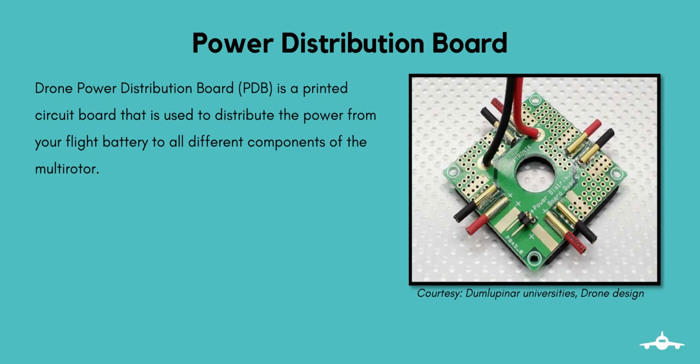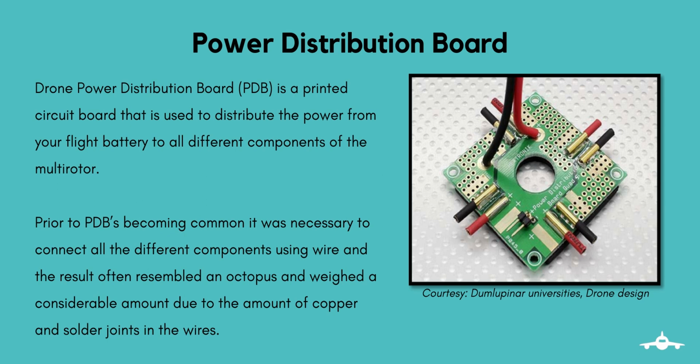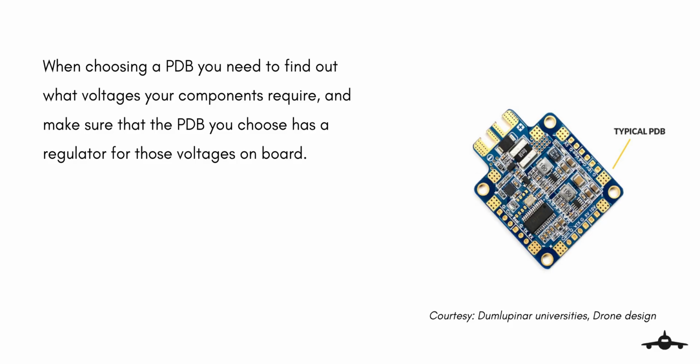Power distribution board. This is the main element of unmanned aerial vehicles of the multi-rotor type, which is responsible for distributing the power of the power system between the different motors. This board is a printed circuit capable of withstanding high levels of current that has a series of ports in which the different elements are connected. There will be a port through which the terminals of the battery will go. The internal circuit of the board will be connected to the power outputs, whose number will depend on the number of rotors the aircraft has.